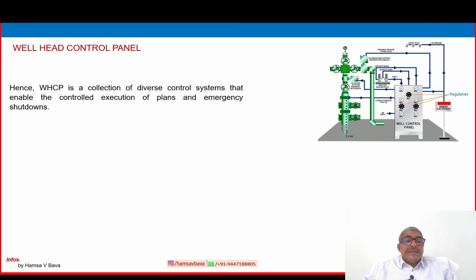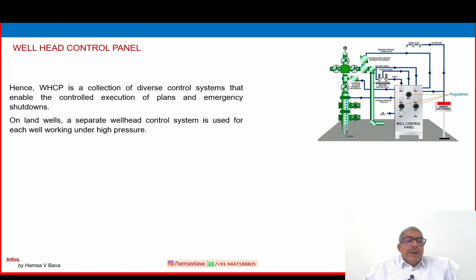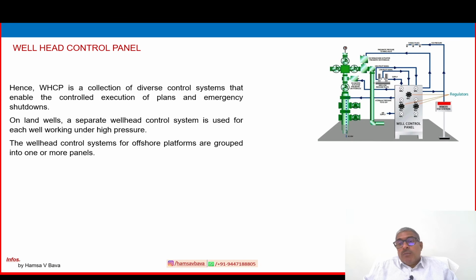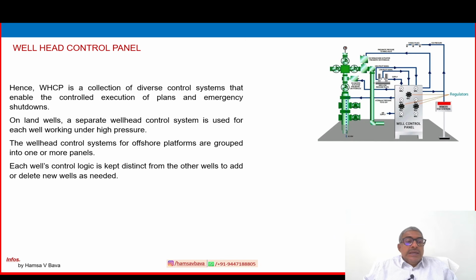Hence, the wellhead control panel is a collection of diverse control systems that enable the control execution of plans and emergency shutdown. On land wells, a separate wellhead control system is used for each well working at high pressure. Land well means desert onshore. The wellhead control systems for offshore platforms are grouped into one or more panels. Each well's control logic is kept distinct from the other wells to add or delete wells as needed.